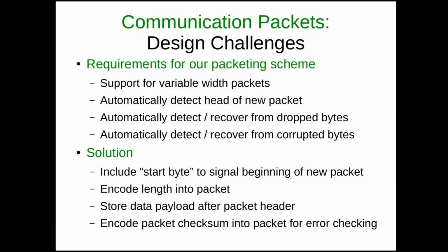If we just stream out those 2 bytes, byte 1, byte 2, then byte 1, byte 2, then byte 1, byte 2, the microcontroller may miss one of those bytes at some point, and it doesn't know which byte belongs to which. So it may get byte number 2 first, and then byte number 1, and if it doesn't know when the start of that data transfer began, it doesn't know which byte belongs to which logical value. So because of this, we need to use what's called a packeting scheme.